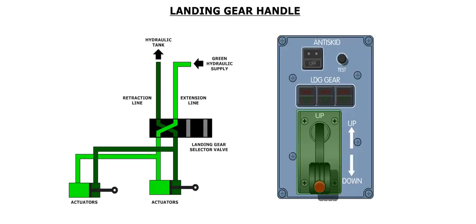The landing gear is operated by the landing gear control lever located on the flight instruments panel. The lever must be pulled out in order to move it. The landing gear cannot be retracted if one gear shock absorber senses a weight on wheels condition. Click on the landing gear control lever to continue.